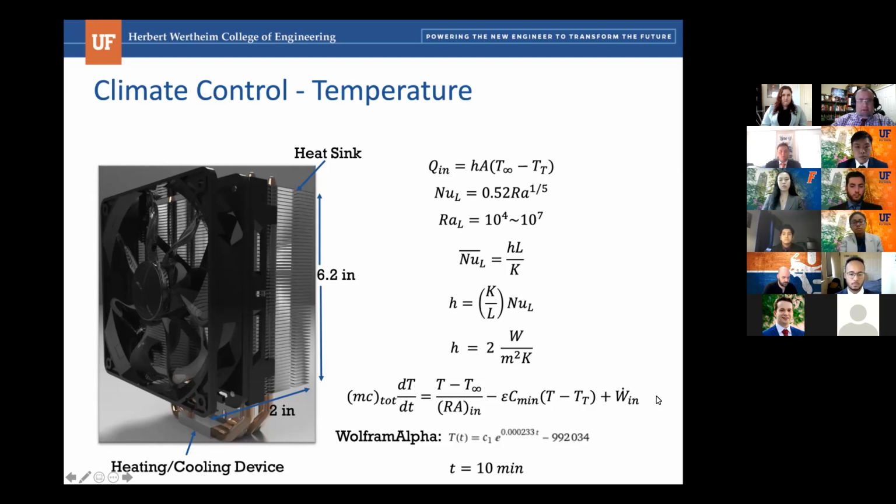Okay, with your permission, I'm going to draw a little bit on here. So we're talking about this term that I'm bracketing. Yeah, exactly. Okay, I think I understand now. So this H value that you've calculated, I hate to put a big red X through this, I feel like one of my MIT professors who used to do this all the time. This H value is the convective heat transfer coefficient if there is no fin tube heat exchanger in place. Exactly.